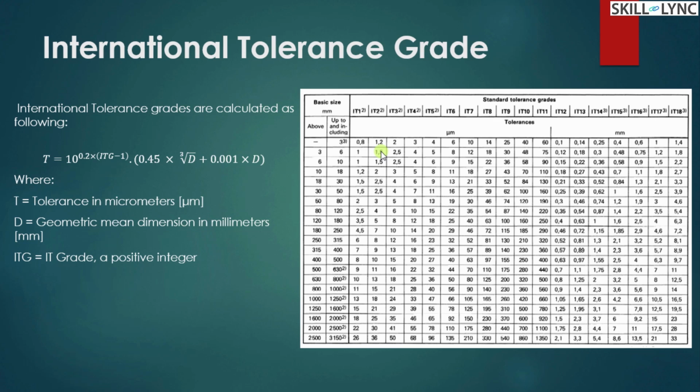So this is typically how your IT tolerance grades are defined in your standards, and you always have to keep this in mind. This is strong engineering practice when you design a component. When you design a component, you also define the process that needs to be followed, and based on the different processes you have to draft your drawings and specify the tolerance according to those processes. So this defines a very good engineer who has a good grasp of this condition.